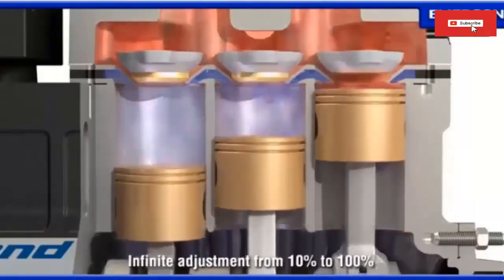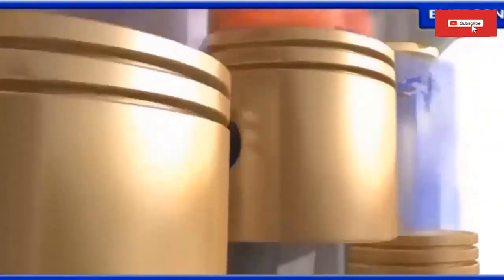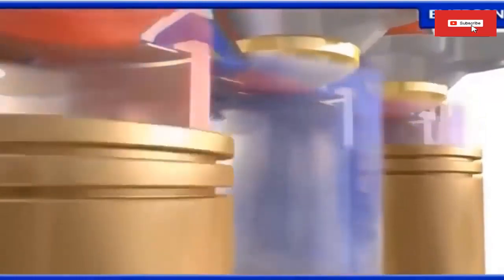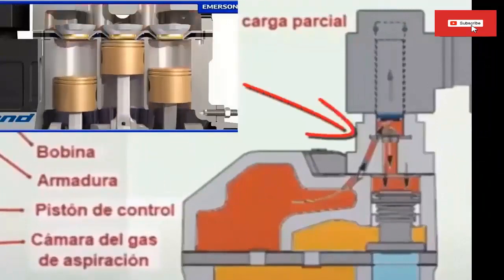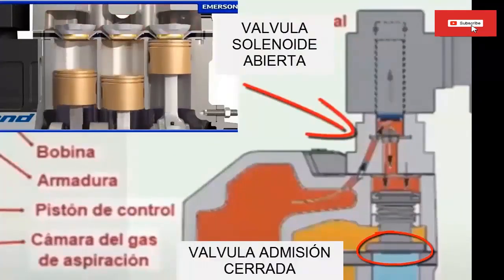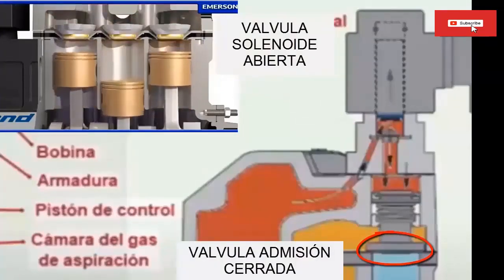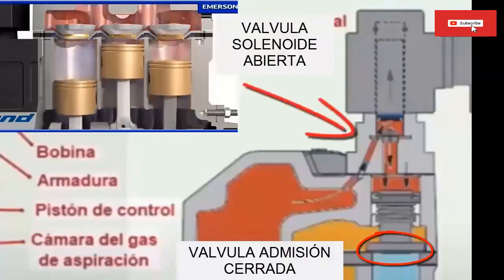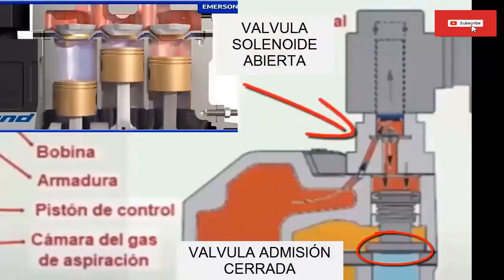7. In response to a decreasing load, an electronic controller sends an electrical current to activate a solenoid. 8. This solenoid valve diverts the compressor discharge pressurized refrigerant vapor to the top to shut off the flow of refrigerant vapor to the cylinder suction. 9. Even though the piston continues to travel back and forth within this cylinder, it no longer performs compression as it cannot absorb refrigerant vapor.